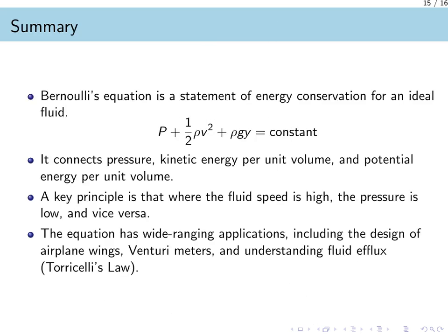To wrap up our discussion, let us summarize the core concepts of Bernoulli's equation. At its most fundamental level, this equation is a statement of energy conservation, but specifically tailored for an ideal fluid in motion. The equation states that the sum of P plus 1/2 ρv² plus ρgy is constant along a streamline.